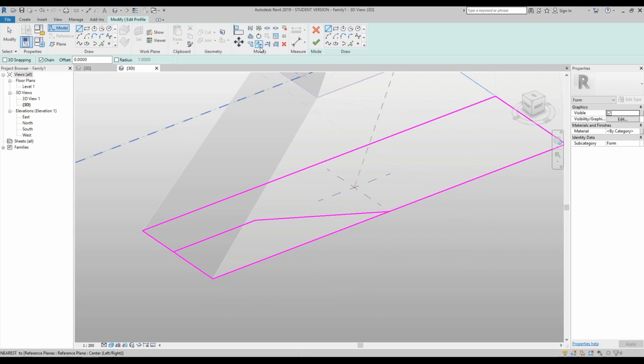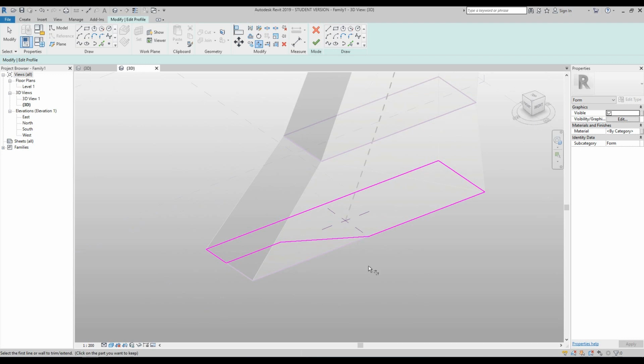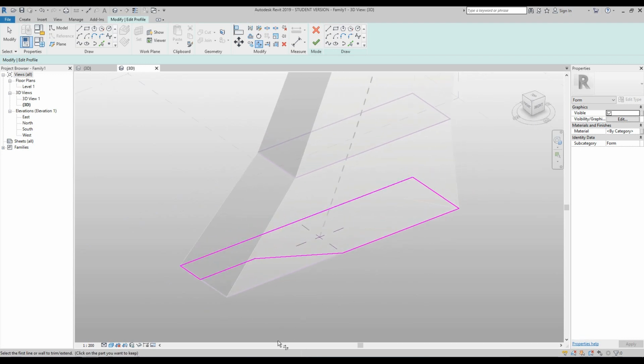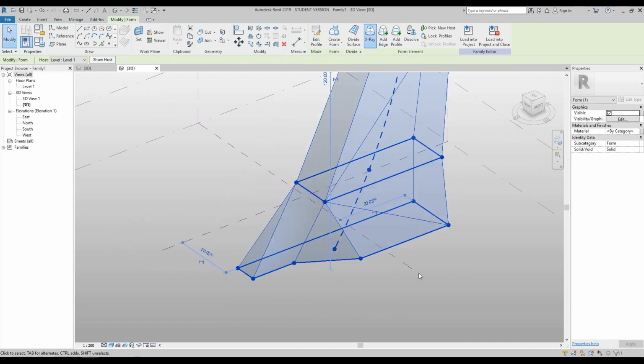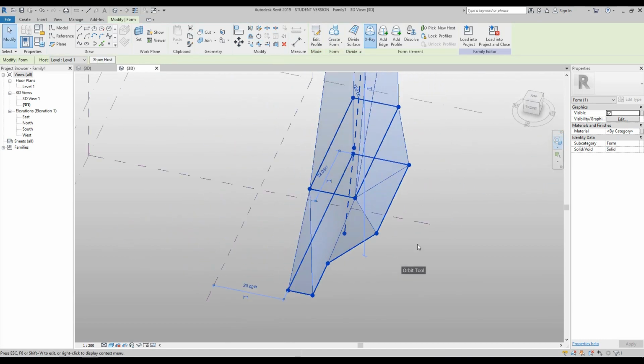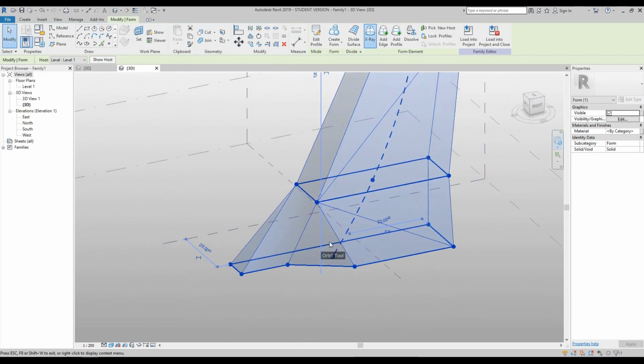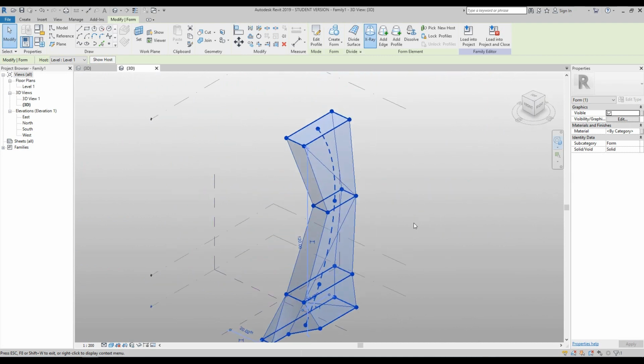And then we go up to the trim extend to corner tool, and we're just going to close the chain lines, close the whole chain, and you will notice that when we press the green tick, the geometry will change. So once you do that, you see exactly we've got more edges and a more intricate base to the building.